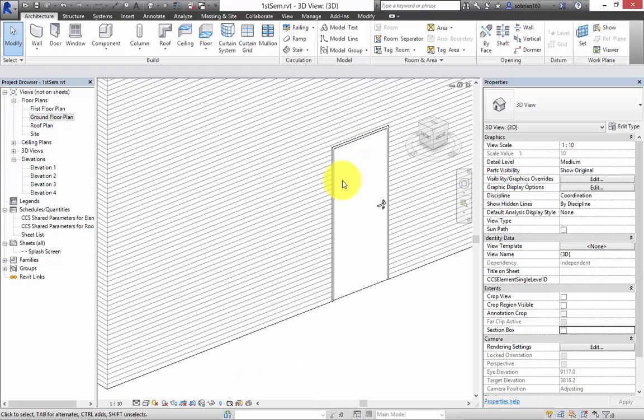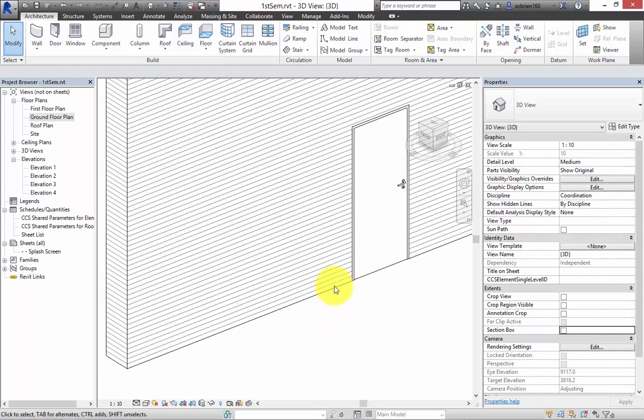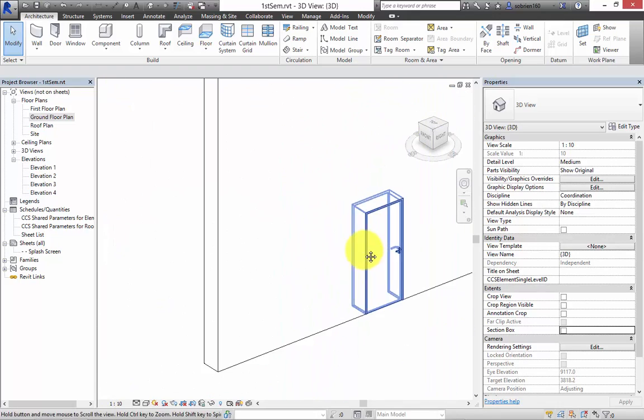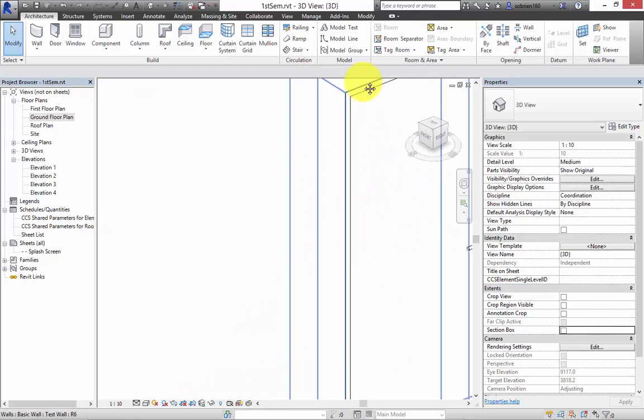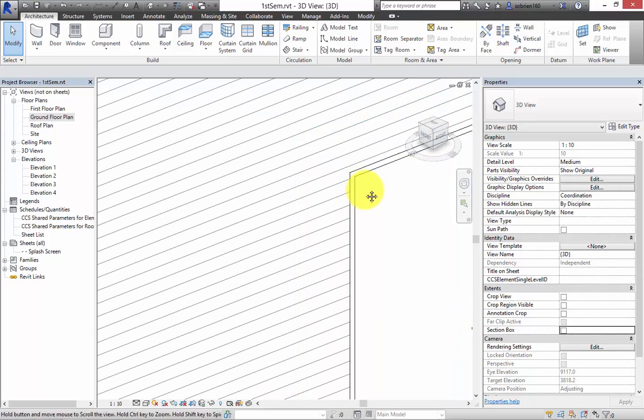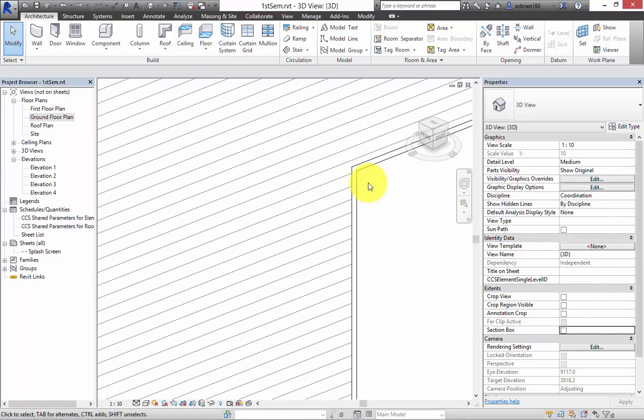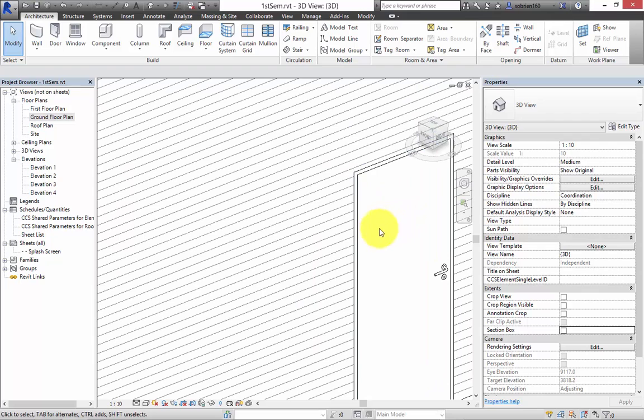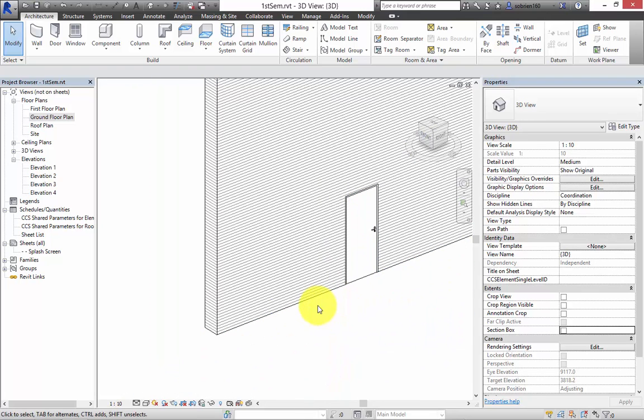The other thing I just want to talk about here, just while we're on the subject of the external pattern, is, okay, it's nice it makes a pattern of bricks, but often it makes a pattern of bricks in the wrong position, and you want to get it in the correct position. So you can actually adjust where the bricks are built. Let's say, for the sake of argument, that this brick here is supposed to be lying directly on top of the door because that's the way it's being constructed. We can actually move the entire pattern so the whole thing lays in the correct position. So the way to do that is the tab button on the left here.